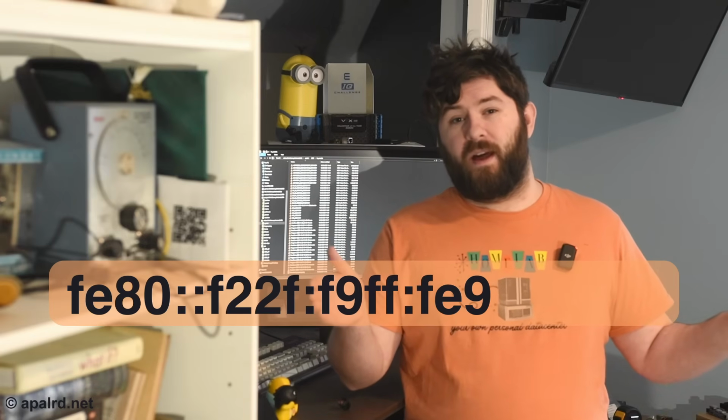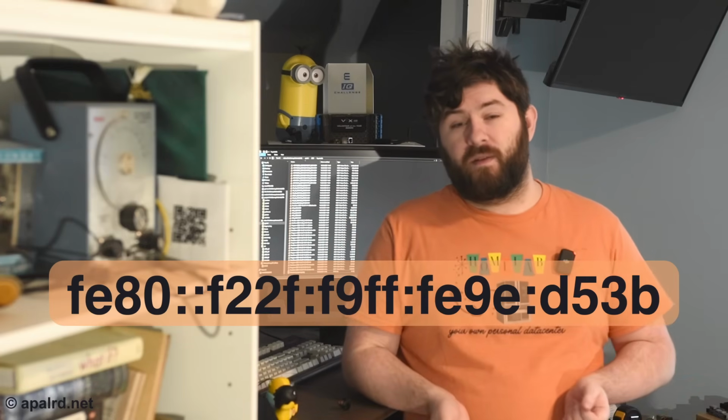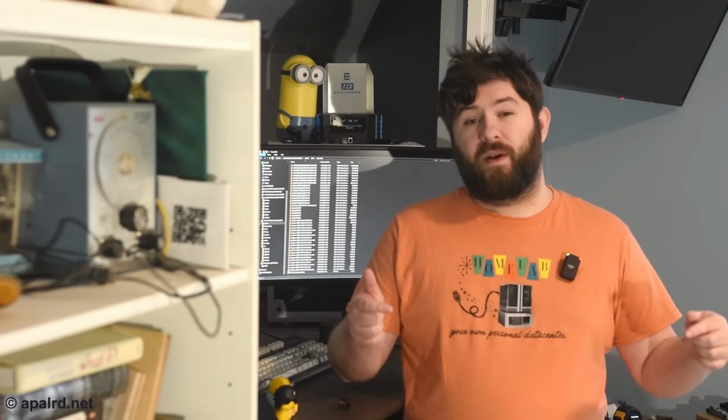So you start with FE80, and then they have a 64-bit unique identifier that comes from the MAC address. So each of these boards has a unique MAC address. Each of them has a unique link local address. It just works. Now, because IPv6 normally has more than one address per interface, and actually the ESP32 supports up to 5 per interface, so we have our one link local and up to 4 more, I can give them global addresses that are routable around the world if they need to reach out to the cloud, but they can still use their local addresses to talk to each other to negotiate the puzzle.